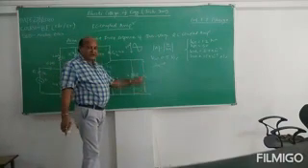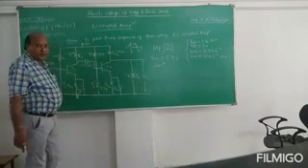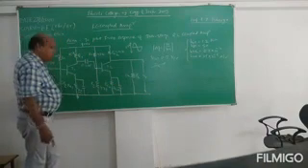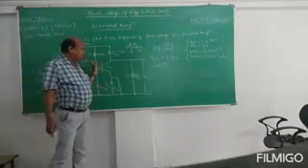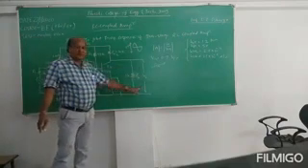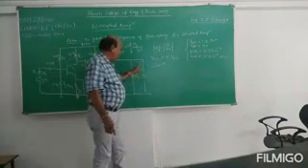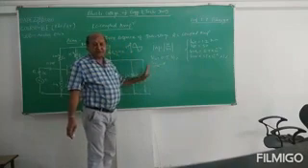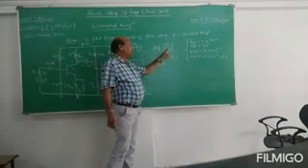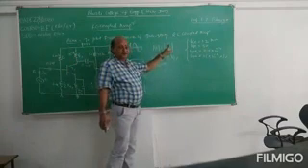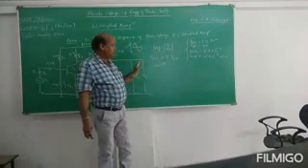We will connect the second channel of the CRO here, and the first channel is connected to the input, where we apply the signal from the function generator. So at the input side is the function generator, and at the output side the CRO. Accordingly, note the output voltage for every frequency, and then calculate output upon input. Input is fixed, output will be varying at different frequencies. So calculate this gain, the amplitude gain.